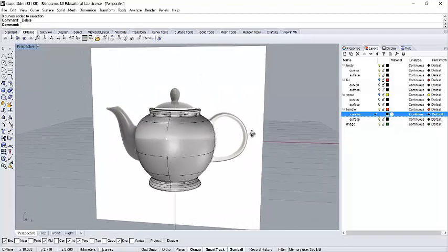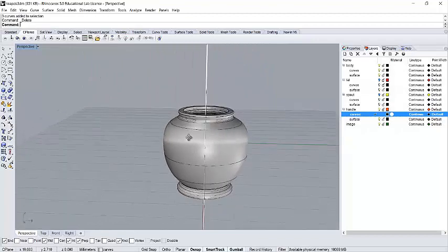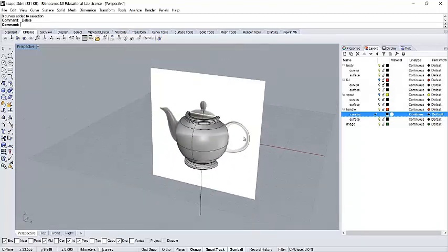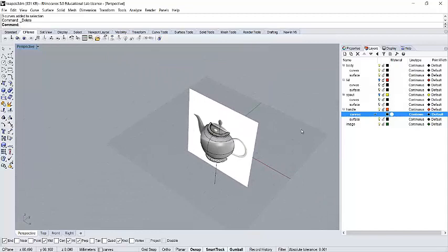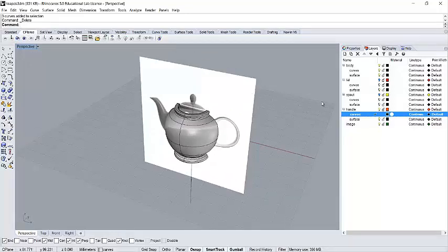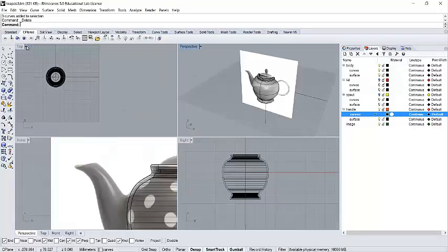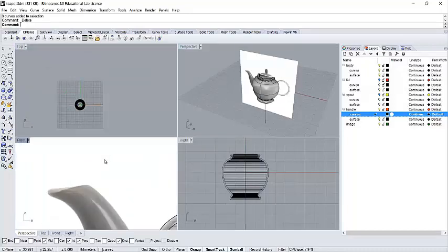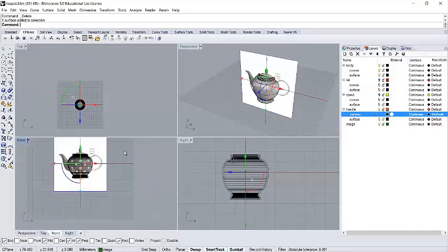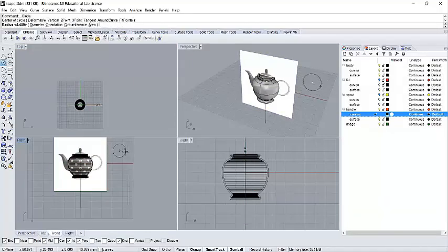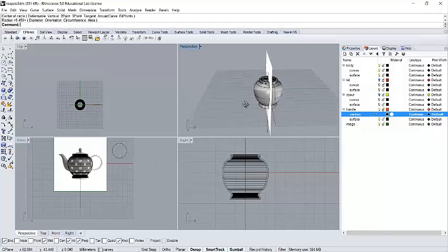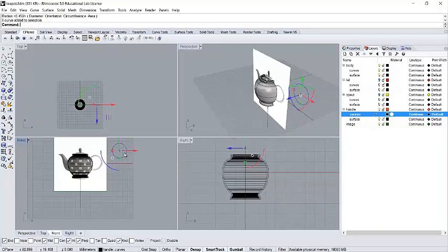Now this is where it can get a little bit tricky. We're going to create our own C-planes. At the moment there's the active C-plane. Here's the C-plane tab, in this window on the ground where you can see that grid. If we jump into these other views, the C-plane is vertical. If I see in the 3D view, as I try and create there, I'm actually creating in that plane. So there are existing C-planes, existing work planes that you can work on.